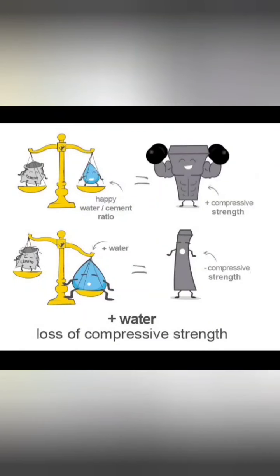If the water content is more in our concrete, it will be good in workability. If the workability is more, then it is going to be placed easily, compacted easily, and finished easily. But on the other side, there is a disadvantage. The more quantity of water which is left in the concrete upon hydration is going to evaporate from the place, leaving that place empty. So we are discussing the water cement ratio.